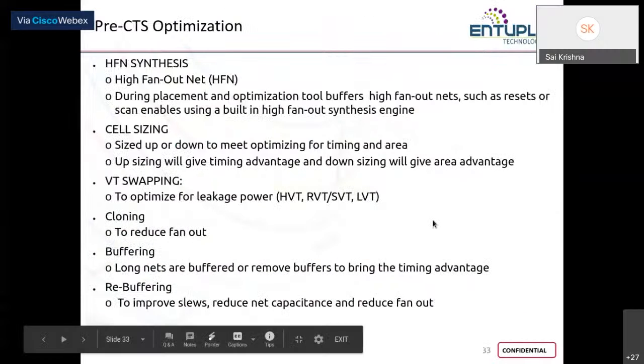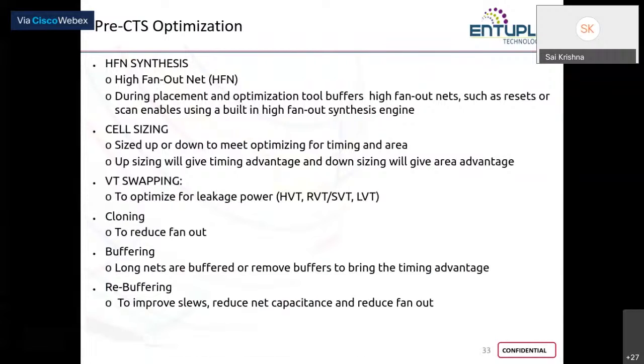And then you also check for, and along with them, basically your area and power might be almost the same as that of your synthesis report. But when it comes to timing, there may or may not be certain violations. And with respect to timing, there are certain extra factors that you have to also look in physical design.